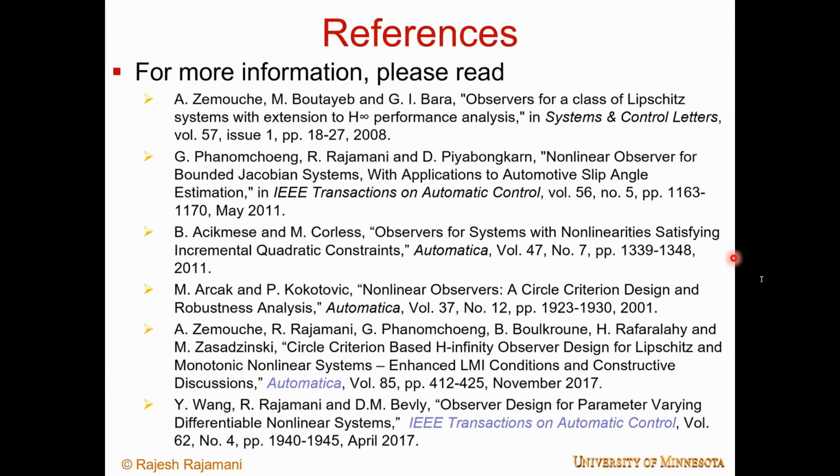So there is some question about the condition number and LMI constraints, and is there a relationship between the performance of the observer and the condition number? In general, by achieving a good condition number of the eigenvector matrix, you make the system more robust.